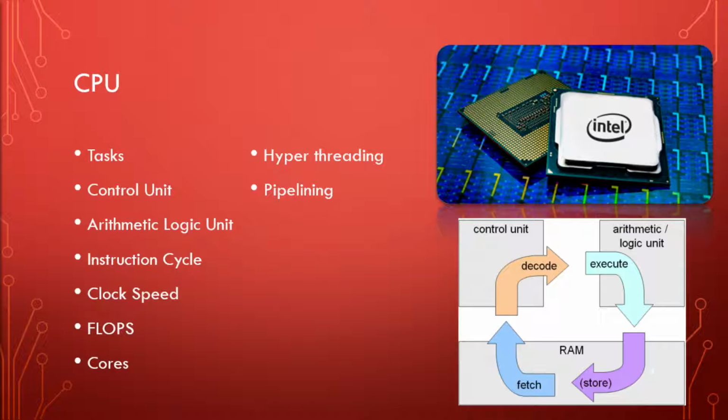What pipelining is, it's kind of making you do 2 things at once. First, I'm going to tell you to do something. And then as you're doing it, I'm going to tell you what the next thing you should be doing is. So it's always basically processing 2 things at the same time, or maybe 4. So if we take those instruction cycles, it always has the next fetch, decode, execute, or store ready to be happening. So it's, in theory, like doubling the speed, because it's never just waiting around. It's always just like half a step ahead.